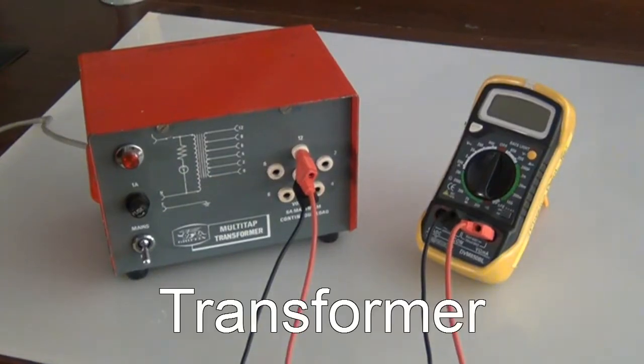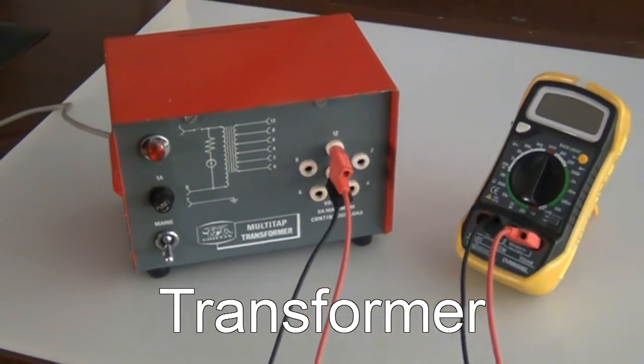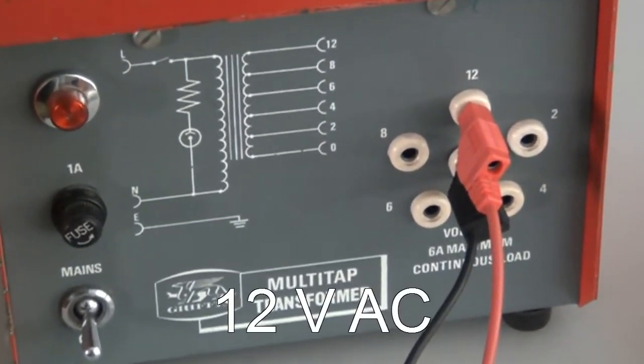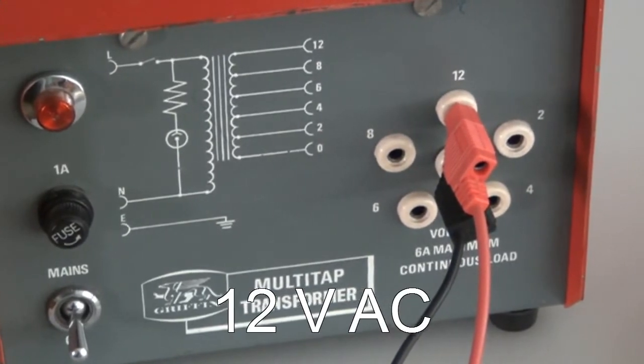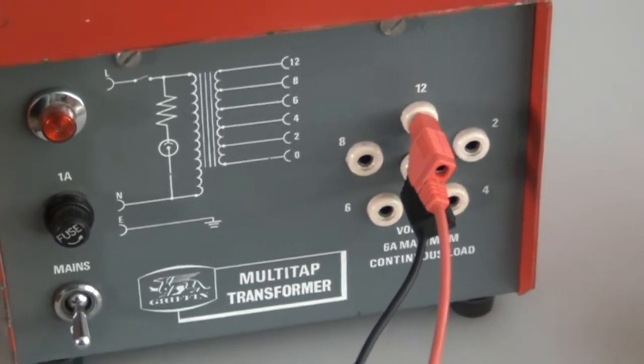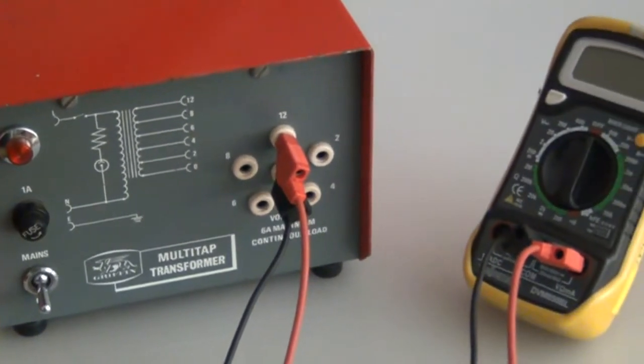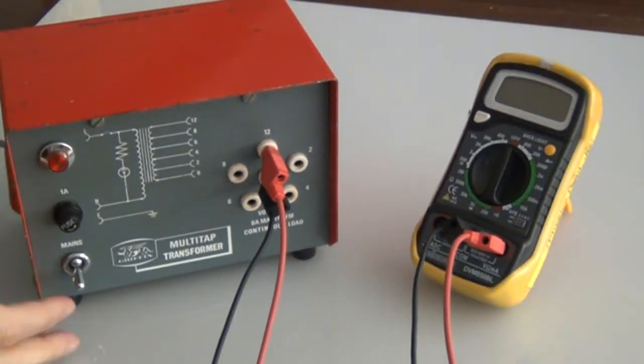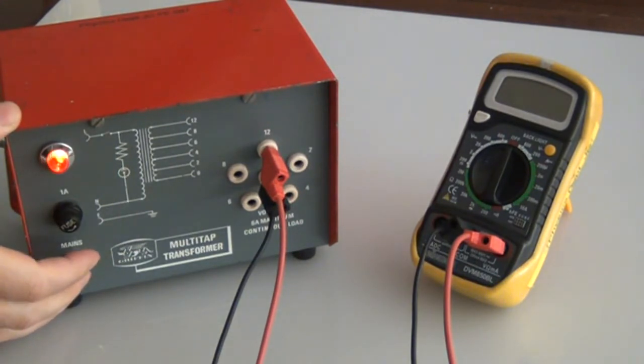We shall start by measuring AC voltage. For this experiment we require an AC transformer. The output is AC, and we intend to measure 12 volts AC. And this is connected directly to the multimeter using the center terminal and the right hand side terminal. We switch on the transformer